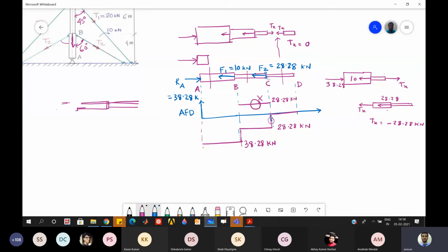Okay, so there are some things happening, and if we do a detailed analysis using some computational code like finite element software, ANSYS, Abaqus, probably we bother about those things, the stress concentration and all. So we'll treat that the axial force between these sections is fine. And at this particular C point, there is a jump, and that jump we will just represent by a line. Okay. So this is it. So this is our axial force diagram.